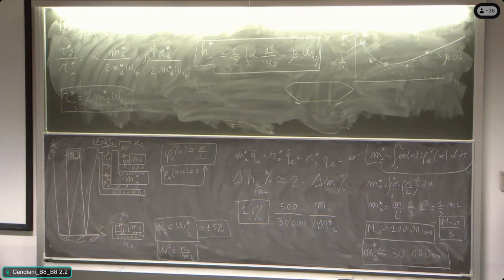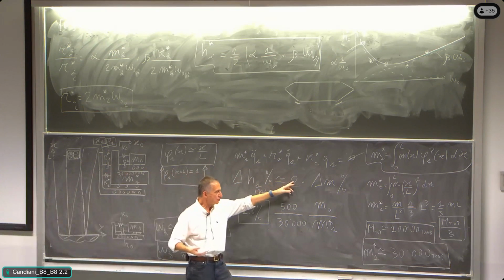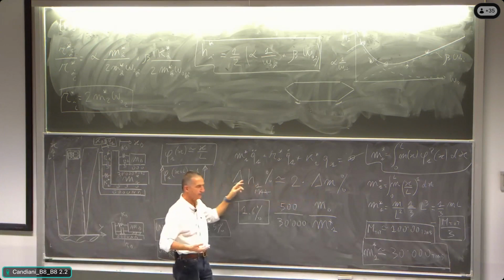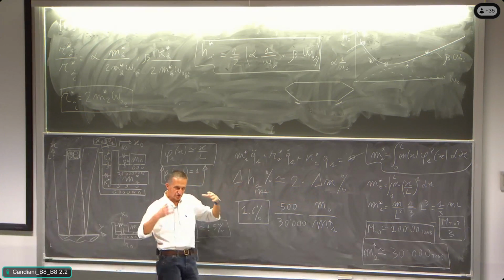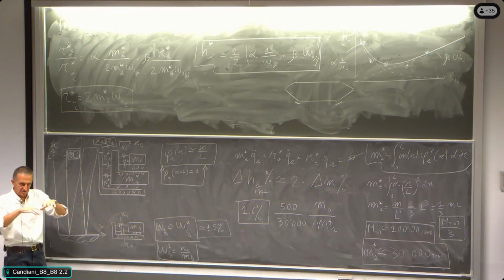let's say, if it was 2%, if we are adding a mass that is 2% of the modal mass, the maximum increase in non-dimensional damping is twice this percentage. It will be 4%. All right? So the rule of thumb of the tuned mass damper is that when it is best tuned,